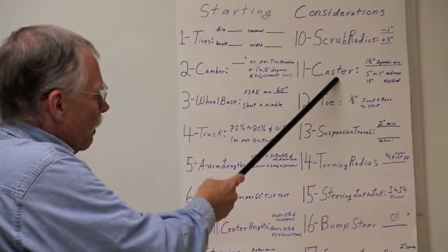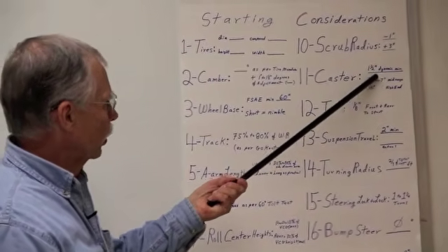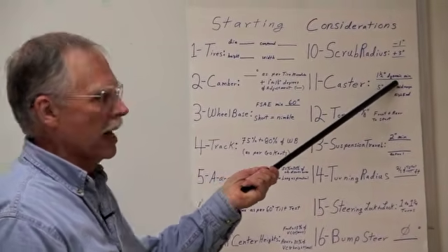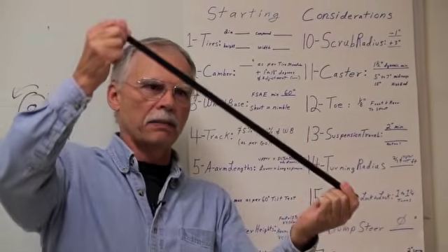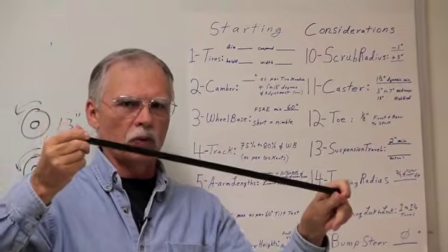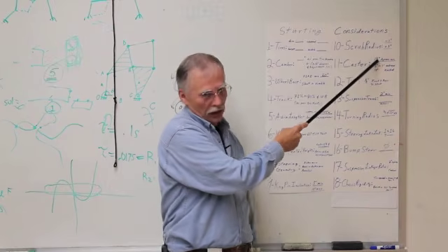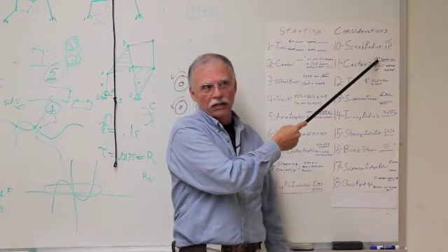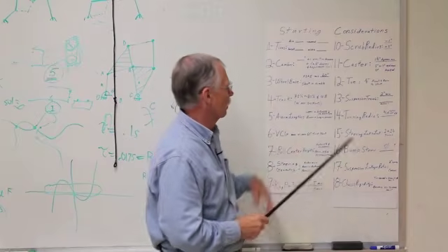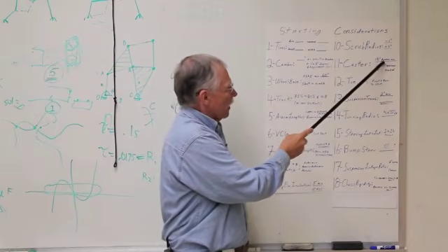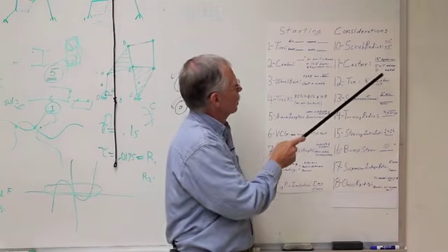The rule of thumb about caster is never ever let it go below 1.5 degrees at the dynamic maximum load on the vehicle. That's when the vehicle is braking and the back end is coming up and the front end is squatting. You never let it go to 0, or goodness sakes, do not. It's horrible if it goes negative. If it goes negative, you're going to get violent shimmy in the front wheels. It can be really severe. Dynamically, 1.5 degrees under worst case conditions.